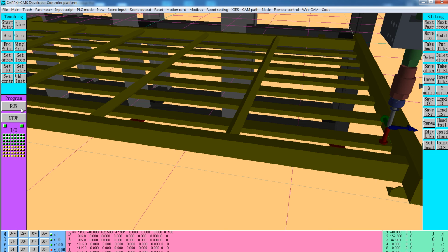It seems okay. Then we have to duplicate to another side with 10 millimeters to the edge. The total width of the plate is 37. Subtract 10 on this side, subtract 10 at that side to get 17. So we duplicate with plus 17.